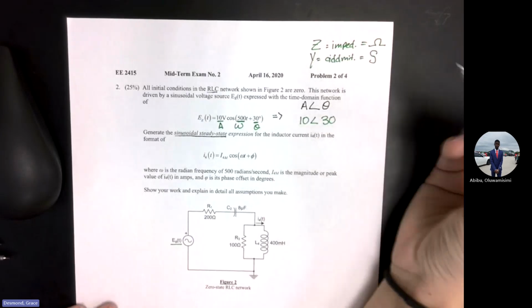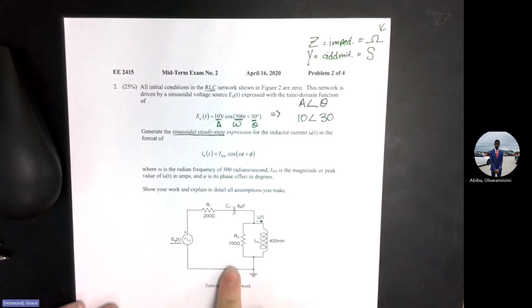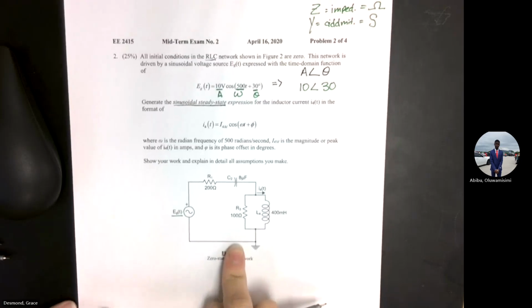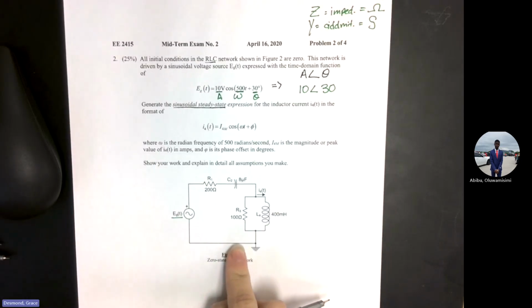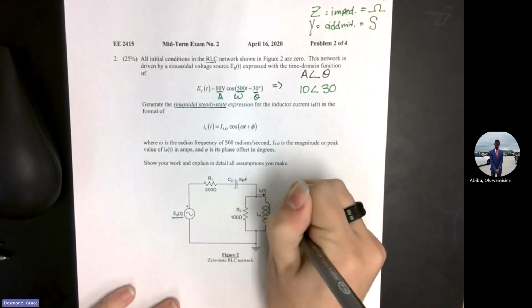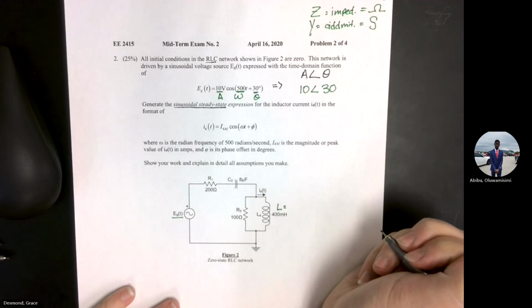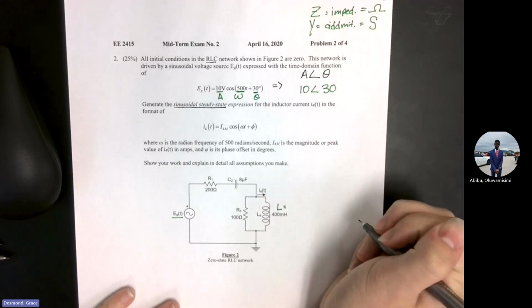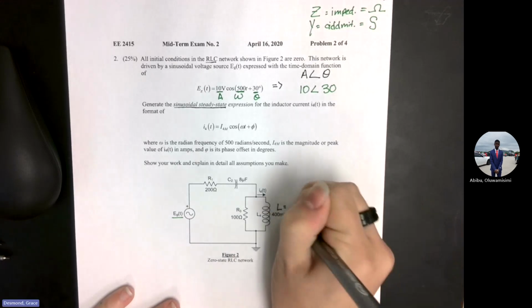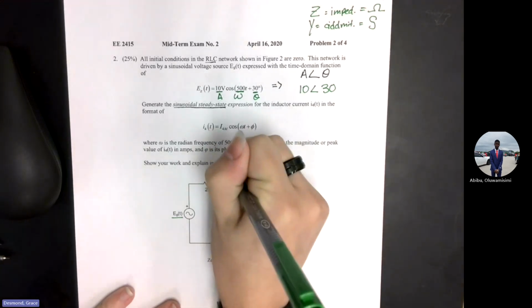So, like I said, we're going to use impedances because ohms are easier to work with whenever it comes to just a loop. So now we need to remember, we need to make all of these into impedances. So what is the equation for L impedance? It's J omega L. And then what about capacitance?